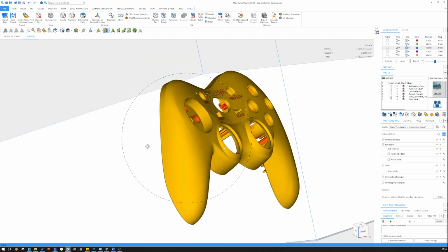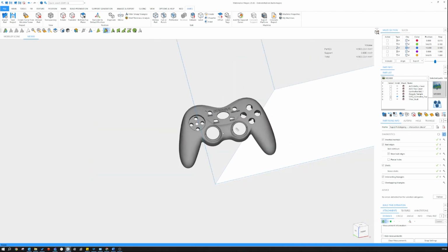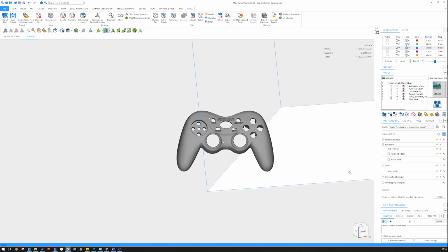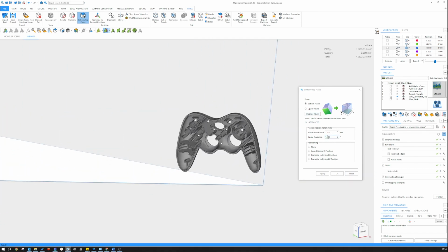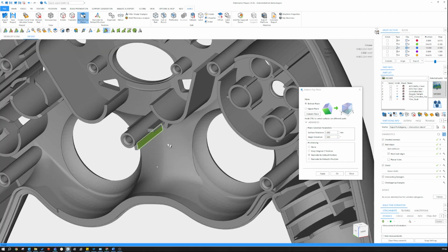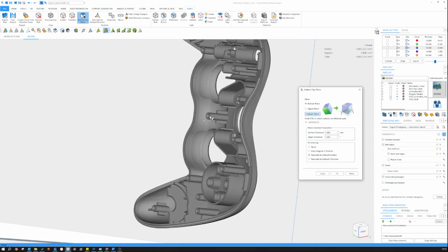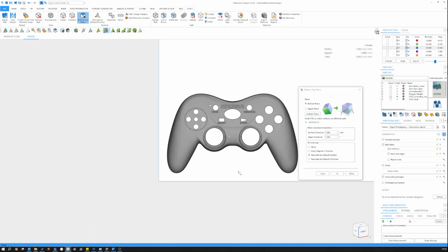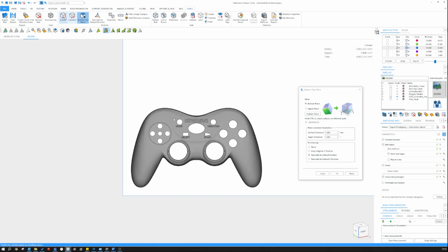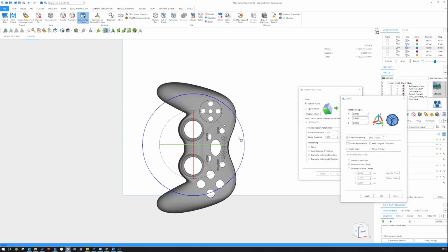Now we are happy with the suitability of the geometry, we can start looking at orientating the part for best success. Part orientation is a key area in ensuring accurate parts that are fit for purpose and can be built reliably and repeatedly. Every part will need to be orientated based upon multiple considerations of part quality, accuracy, application requirement, and manufacturing needs. Almost all orientations are a compromise of these elements, and understanding what elements are being sacrificed in order to enhance others will allow greater opportunity for success when building on the Neo systems.